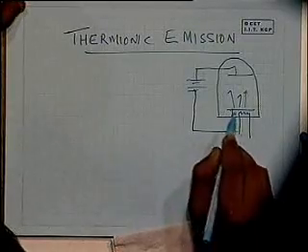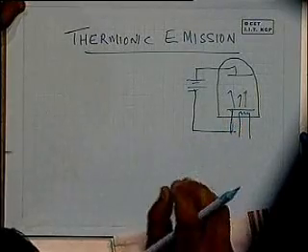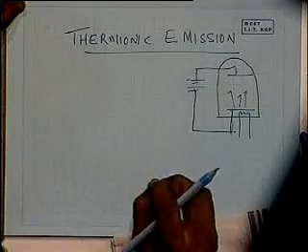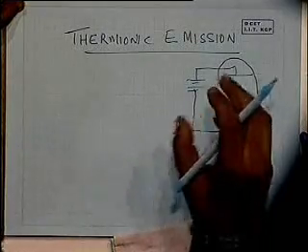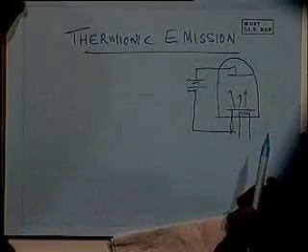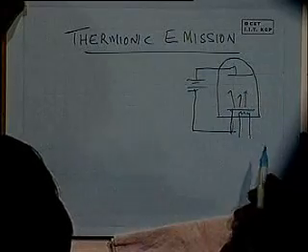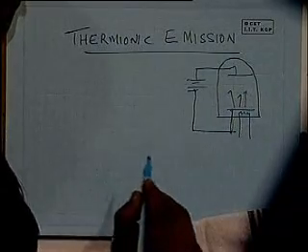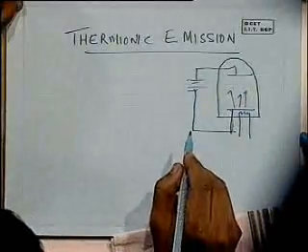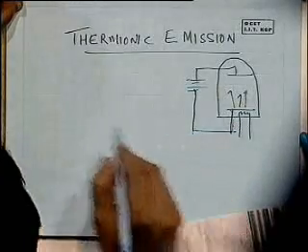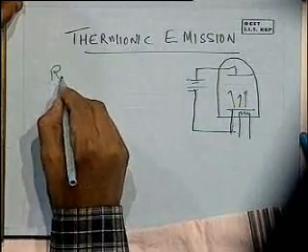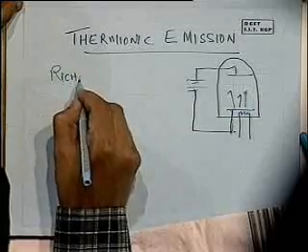This is what is known as thermionic emission. As you heat it up, the electrons get enough energy to go over the potential barrier created by the work function, and so they are emitted. Then we went on to look at how to derive the current density in such a case, and the equation is known as the Richardson-Dushman equation.